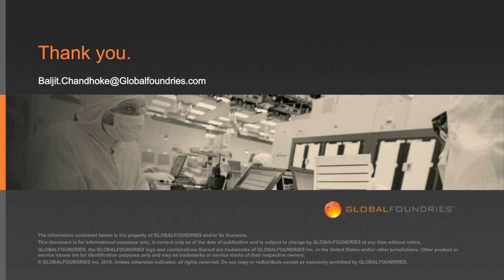Last question. Does the quoted 45 nanometer SOI PA efficiency that you cited include the losses of the on-chip matching network? Yes, it includes the losses in the on-chip matching network. So, yeah, that's correct.